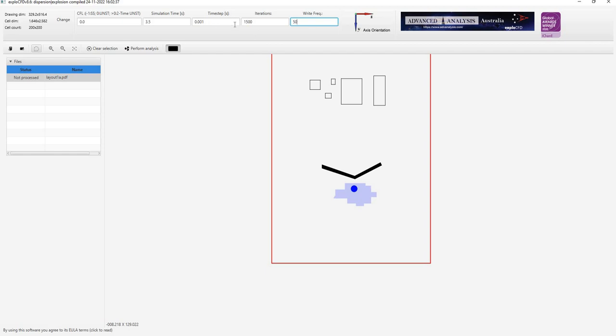iterations, and so the software will run until you reach the product of the iterations times time step. So 1 millisecond times 1500, that's 1.5 seconds. Or this time, whichever comes first. So by leaving this at 3.5 seconds, I'm effectively going to run it for 1.5 seconds. You don't have to set this to 1.5, but if you set it to something under 1.5 seconds, it'll stop there.